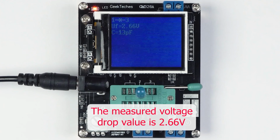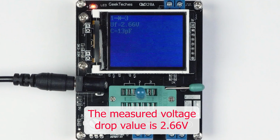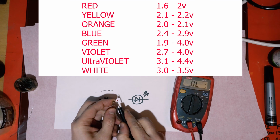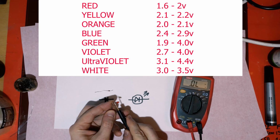Here we can see the universal component tester GM328 measure voltage drop across a blue LED. The value is usually within 1.5 to 3 volts range, and depends on semiconductor materials it's made of, or, rather, LED's emission color. In this table, you can see typical voltage drop values across diodes of different color. In theory, if we check this diode with the multimeter, we're supposed to get a reading of around 1.7 volts.